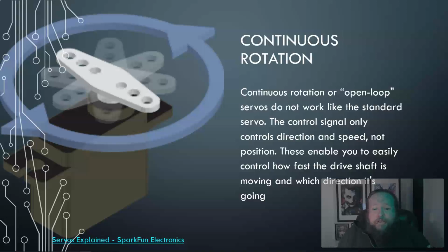Sometimes I've seen these continuous servos used in other moving robots to give more precise control, but then you're connecting it on the outside to wheels and everything else, and friction and what could happen from there. If you were to break down more expensive remote-controlled vehicles, you'll generally find that they have these servos in them for precise control of different things.